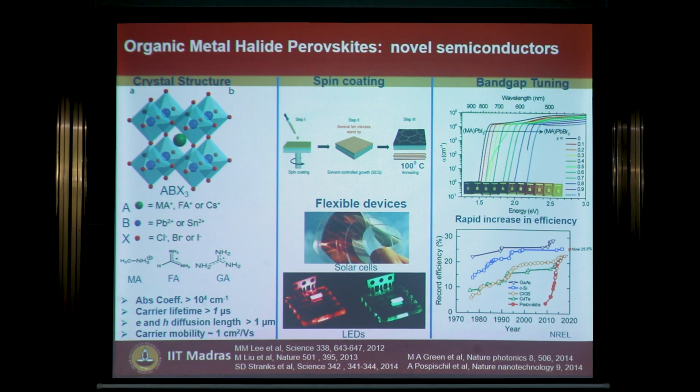Because there you have a lot more loss because of the interconnect and so on. No. Even in the silicon, when we get in the rooftop panel, it's all 21%. We won't cross more than 21%. These are the lab record numbers, which go up to 25. Currently, 26.1% is the single junction crystalline silicon, and the area of that will be around 1 centimeter square. It won't cross to the module levels. Still, it will be at a small area level.